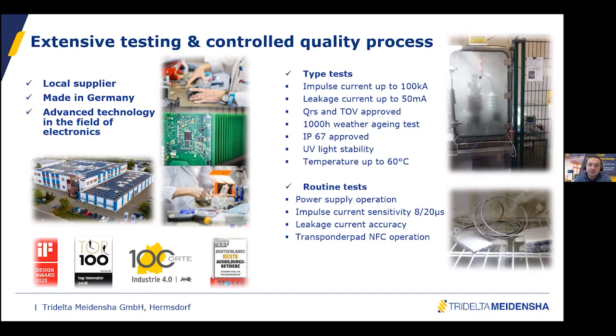And of course, every device is routine tested for the power supply operation, for the sensitivity of impulse current measurement, and of course, leakage current accuracy. And very, very important also, to make sure that the transponder pad can communicate properly with the smartphone and that the information can be collected. So this is done on every unit which is shipped out of the factory.